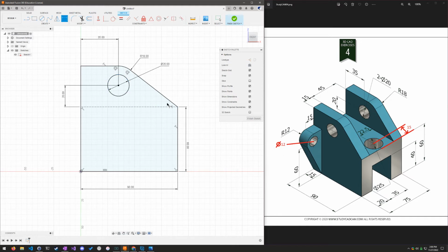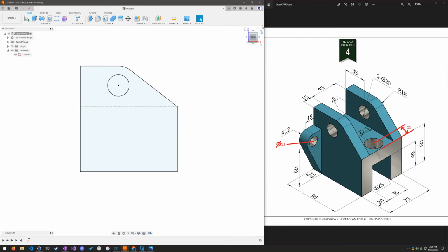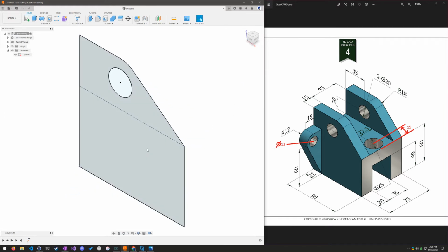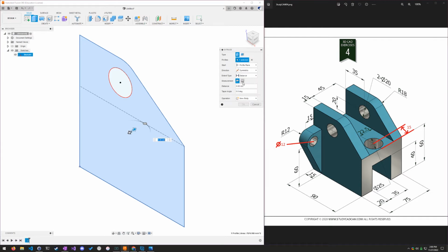But anyway, as soon as we snap that on there, we become coincident, and that's the key aspect. This circle is not just dimensioned for the circle's sake; it's dimensioned because it's the key to locking this whole thing in. Once we realize that the center of this arc is also the center of that circle. All right. We're going to go ahead and finish that sketch. Click home on the view cube and extrude this symmetric and the entire width, which is 75.